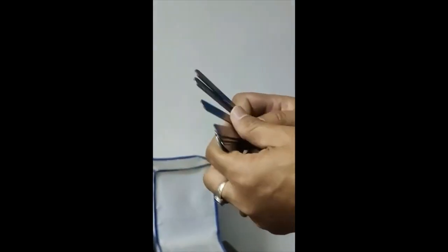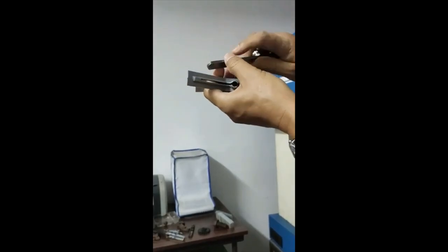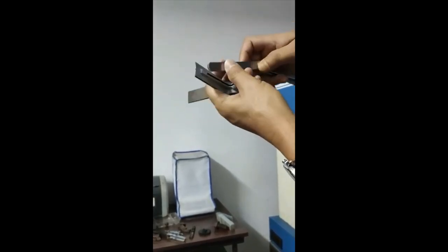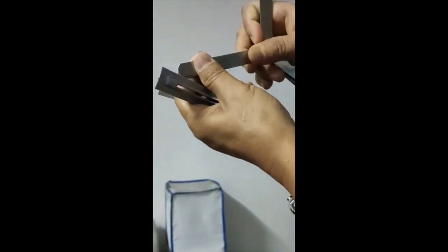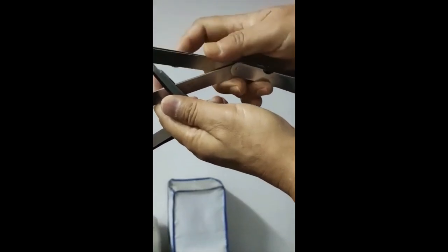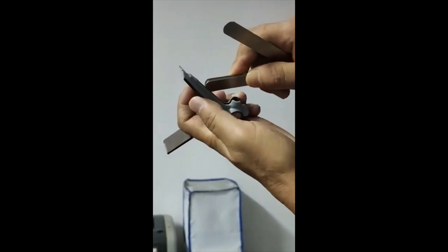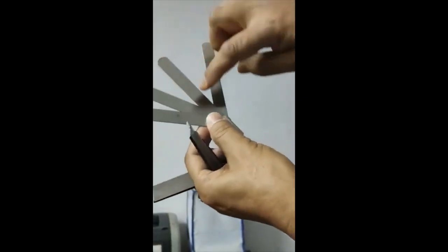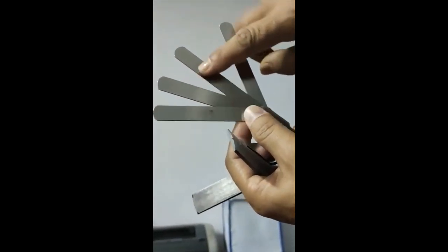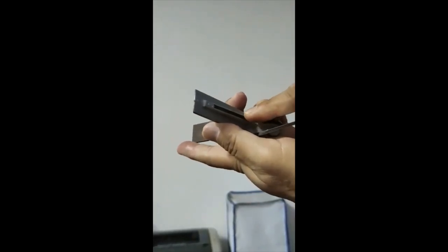After this, I have one feeler gauge. I will use it for gap measurement. This is a gap that you cannot measure with a scale or micrometer, so I will use this feeler gauge. I will insert it in the gap by choosing a leaf, whichever enters with slight friction. I will count the leaves, and the thickness size is written here, and I will add these up to get the accurate value of the gap.